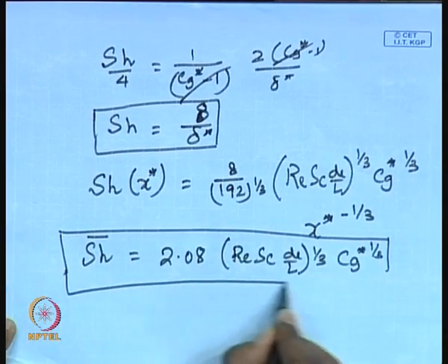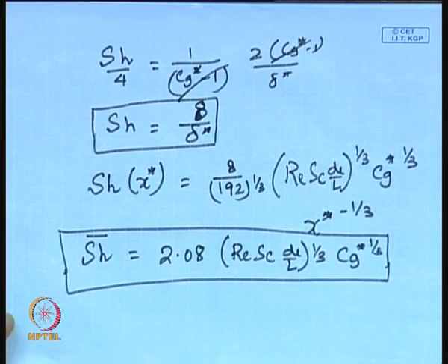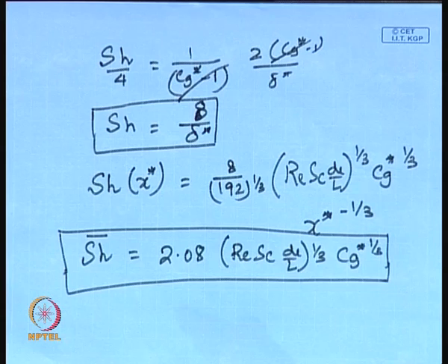So, that is the expression of Sherwood number or mass transfer coefficient in the case of gel layer control filtration, under the 2-dimensional analysis when the mass transfer boundary layer is still developing. Okay. So, that gives more or less an overview of how to obtain the permeate flux or Sherwood number or mass transfer coefficient in the case of a steady state system.